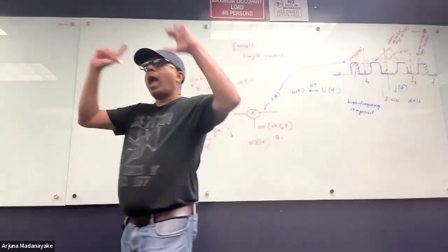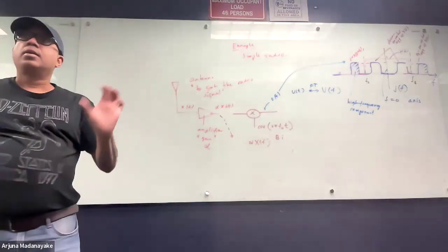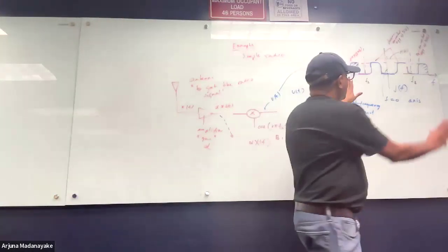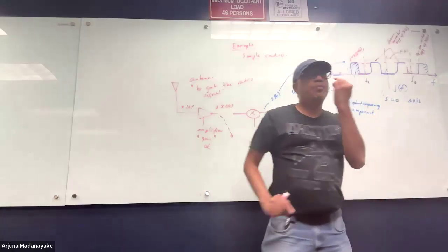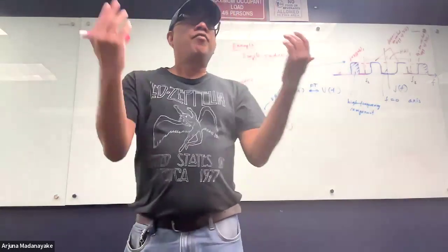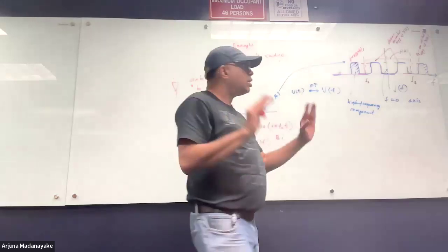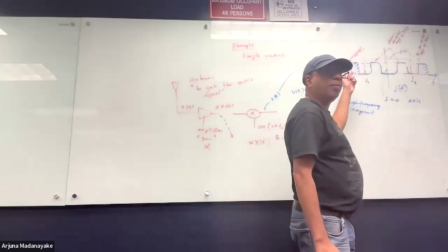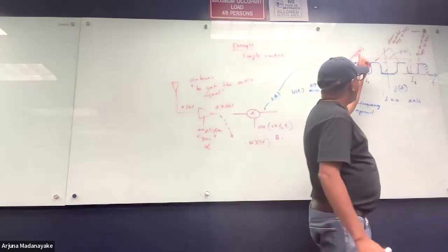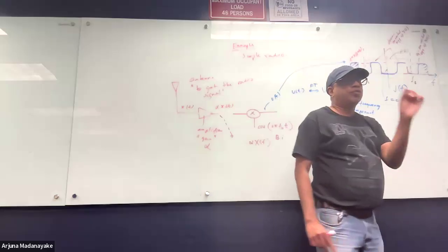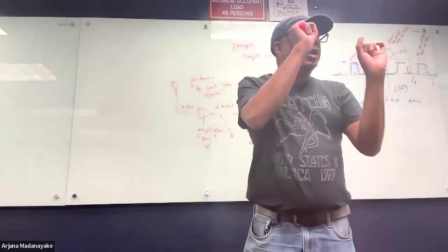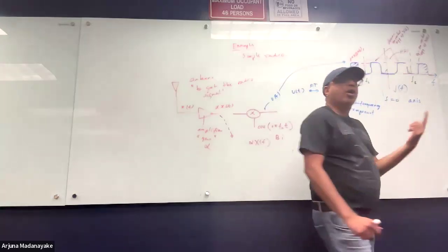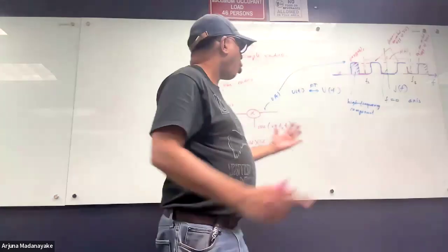You want to apply in a multiplicative way a function that chops off the stuff that we don't want, which is the high frequency component, while keeping the low frequency component. So the function has to have low value, ideally 0, in the places we want to chop off, and high value normalized to 1, because when we multiply something by 1, we keep it. So we have this square wave-like thing, h of f, that we are multiplying this whole output by.